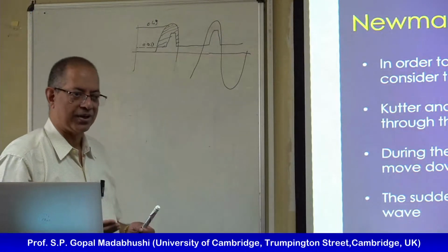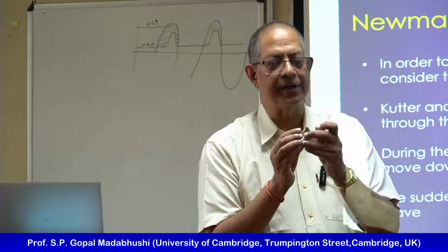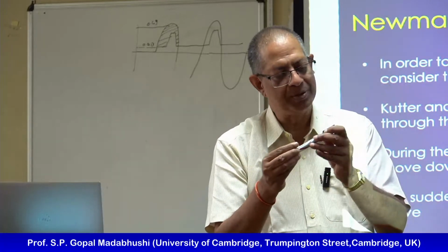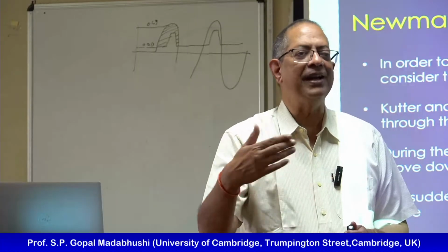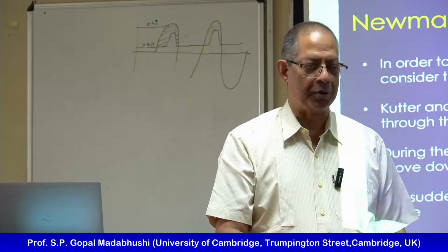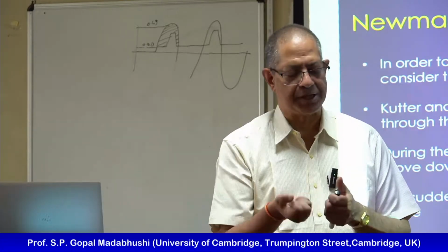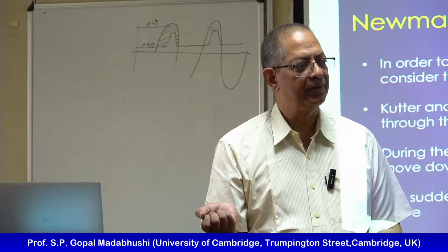And that is quite right, because what the suction is doing is stopping the slope from moving, right? So it moves, stops, right? So if suddenly the pore pressure is going negative and stiffening my soil, I expect a smaller lateral spread to happen.